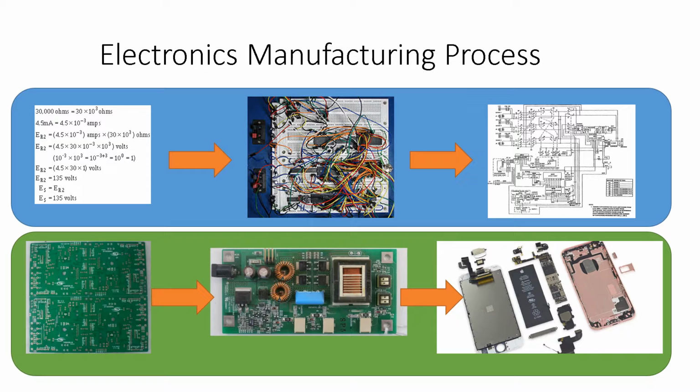The middle one, we call that a CCA, or circuit card assembly. After you've designed your circuit board, you're going to populate it with the parts that the electrical engineer tells you to. So these parts come from the schematic. You don't get to pick them. However, you do have to make sure that all these parts fit. If you put two inductors real close to each other, they might not fit on the board and you're going to have problems. Or if you're trying to build something thin like an iPhone, you're going to have to make sure that all your parts have a very clean and small form factor. So you might change companies for some parts in order to make sure they fit on the board.